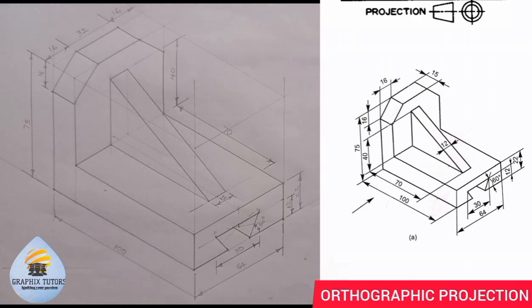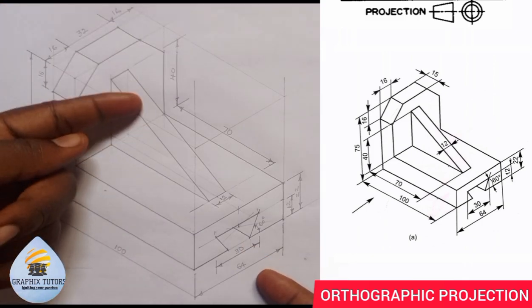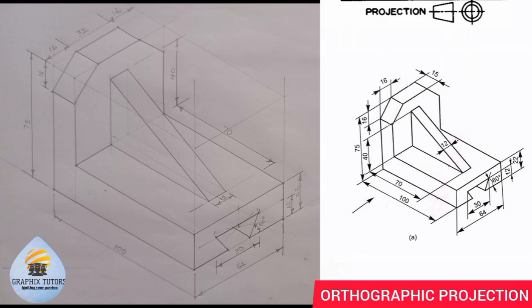Now the first thing is the question says to draw the orthographic projection, meaning that we should draw the given views that are associated with this diagram. That is looking in from this side, which is our point of reference, and that will be our front elevation. So if here's our front elevation, here will be our end view, while looking from the top will be our plan. So what I'm going to do now is draw the three different images that are associated with this diagram.